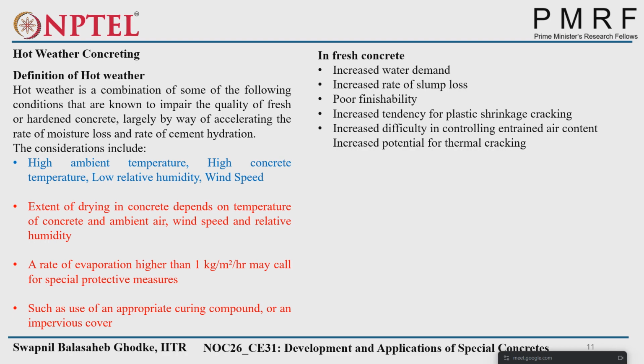Can we avoid hot weather concreting? No, we can't avoid hot weather concreting, because we would be losing time as well. So we have to take certain preventive measures. Another thing is that in the Indian scenario, you'll see most construction in the summer is done at night, because the temperature at night is lower compared to the day. So you'll see most constructions in India at night, in the summer season specifically. I'm not talking about homes or something like that, but most of the large constructions.